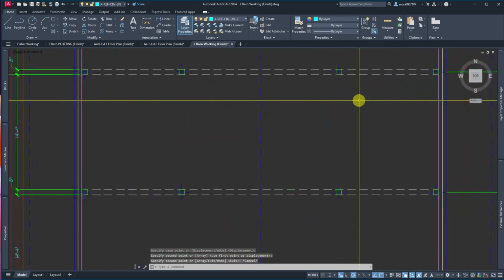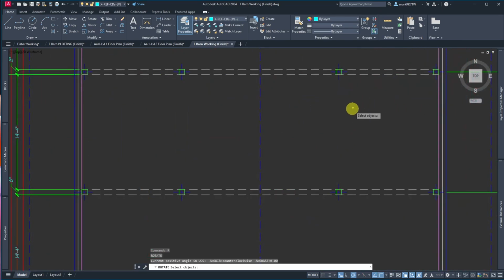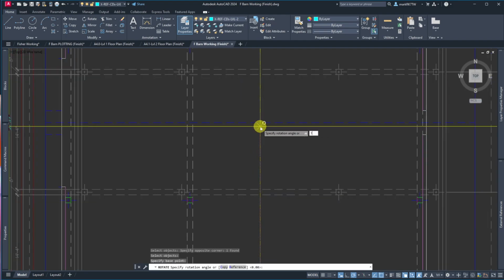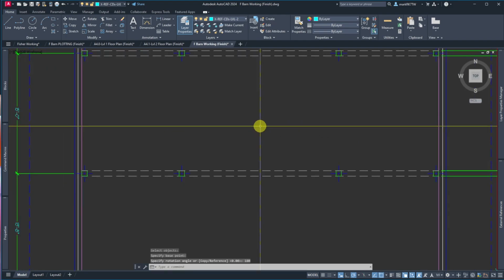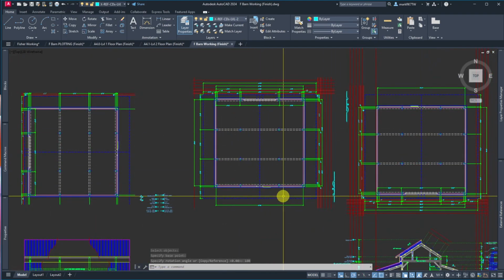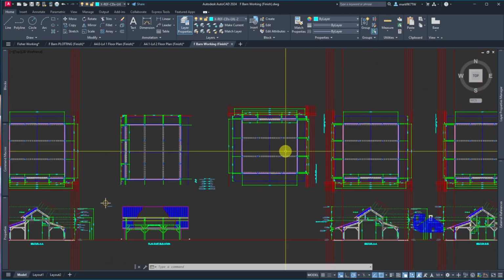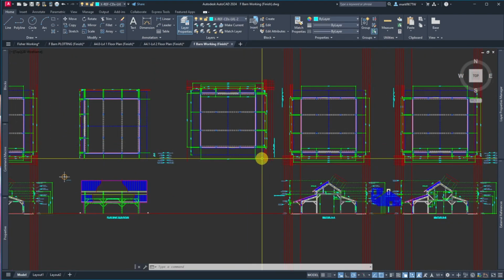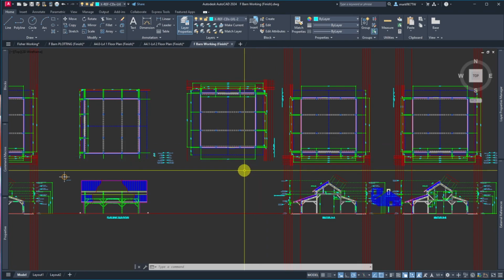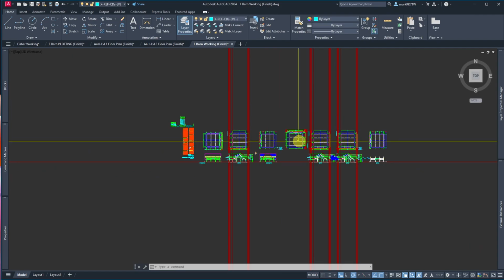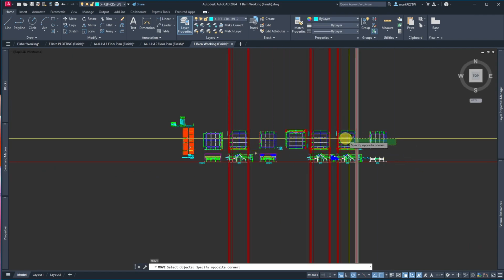So now that I've got it here, I'm going to rotate it around its own center, 180. You can't mirror it. You need to rotate it. This is totally symmetrical, so it didn't matter. But if it wasn't symmetrical, my north arrow, if nothing else, is pointing the other direction, telling me something. So now that all these are up here, these are the bottom floor, so let's move them all.